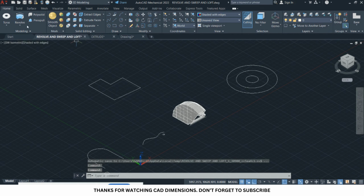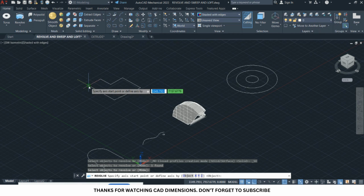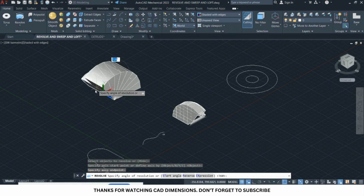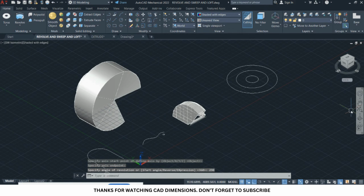Okay, now let's come to the revolve. Click on revolve, then select, press enter, then choose the part that you want to create the revolve. So you realize that you'll be able to create a revolve around that particular side. Maybe this revolve I want to make it 290 degrees. Press enter. Then you're able to create a revolve.